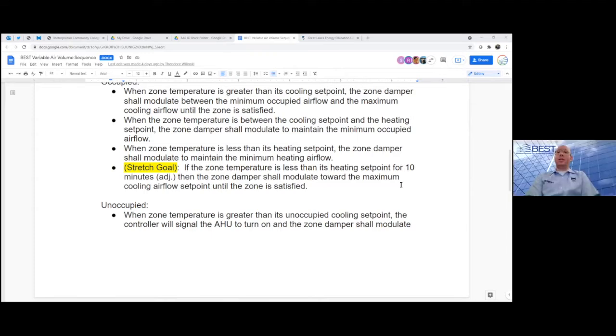Yeah. And our concepts of bringing in outside air as fresh air very well will be adjusted, because there are times in certain areas, whether it's in California when they've got forest fires going, or in the middle of LA or New York City or Chicago, when the air quality is low because of other things going on. So we will be further evaluating, comparing whether the outside air is worse than the air inside the building and what to do past that.